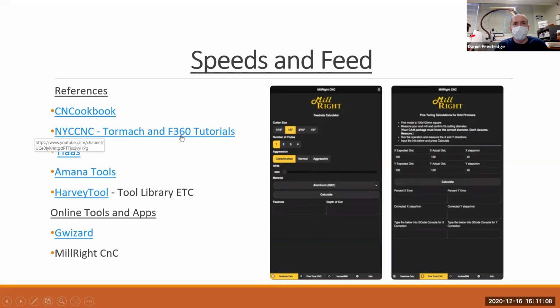of doing a bunch of magical things, like adding, for instance, these things called tabs between your pieces so that everything doesn't vibrate off of your cuts, because you're taking full cuts all the way around. And you don't get that capability from the SolidWorks plugin from the same people called HSMWorks, because of whatever reason.